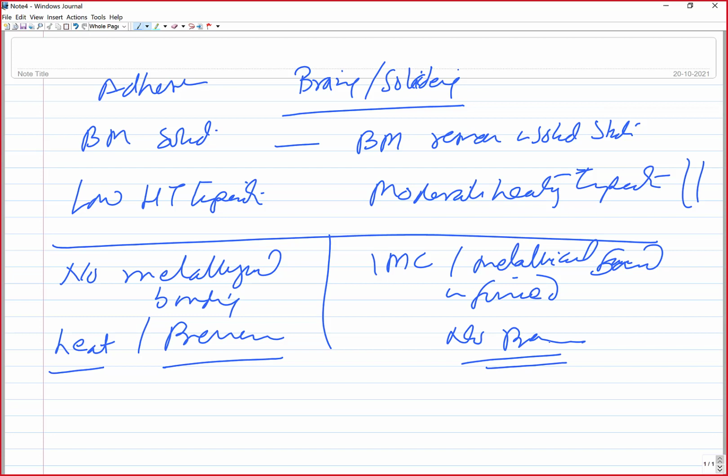Okay. In brazing and soldering, although there are a number of methods, one of the most common is to heat the joint and then place the filler metal outside so that after melting it spreads. Although in dip brazing, the entire assembly is dipped into the molten bath.